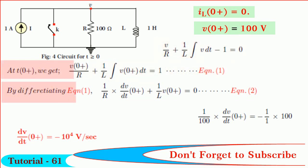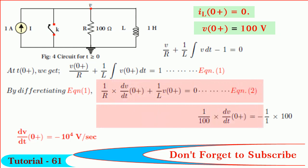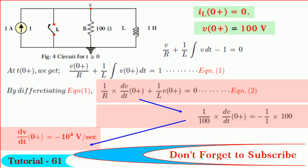By differentiating equation 1, we get 1 upon R into dV by dt 0 plus 1 upon L into V0 plus is equal to 0. By substituting the values, R is equal to 100 ohm, L is equal to 1 Henry, V0 plus is equal to 100 volts and solving, we get dV by dt 0 plus is equal to minus 10 to the power of 4 volts per second.